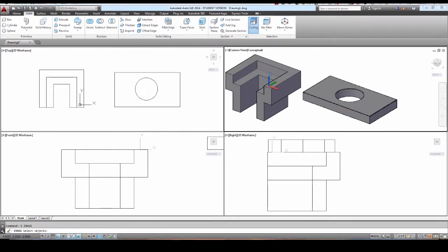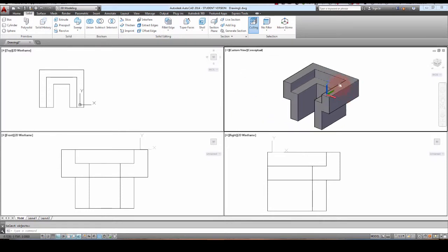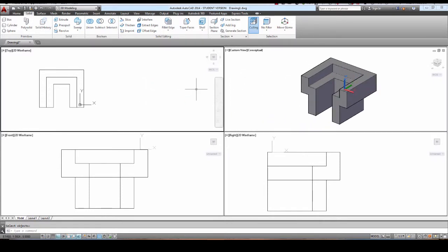So if I want to punch a hole in this object, even though we don't have one, say I want to put a hole in this back wall, where would I do it? I want to put a hole like right here in this back wall going through this. So I wouldn't do it in the top viewport, and I wouldn't do it in the right hand side viewport. I'd do it in this viewport here, the front viewport. So basically what I'll do is I'll just draw a circle off to the side here for a second, just to show you as an example.